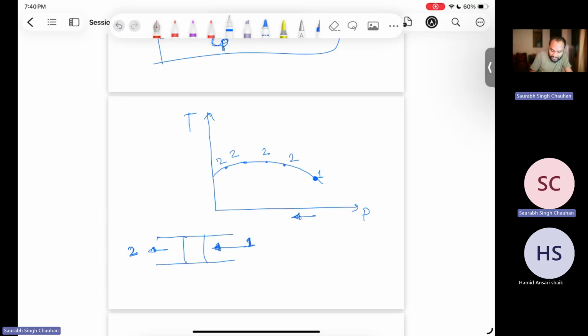Initially, you can see that if you are reducing the pressure, then the temperature is increasing, not decreasing. And after a certain state, after this particular maxima, if you further reduce the pressure, the temperature is reducing. So you are getting a cooling effect. So basically you have to cross this maximum. You can make many isenthalpic lines. So this is, let us say, at a particular enthalpy, H1. You can make more such lines.